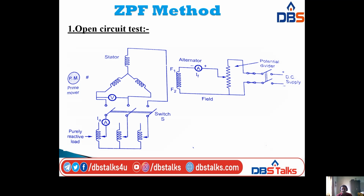This is the diagrammatic representation of the open circuit test in the ZPF method. Here I am taking one prime mover, which is used to drive the alternator at rated speed. Here I am taking a star connected armature winding. It consists of one voltmeter, and this voltmeter is used to measure the open circuit voltage.